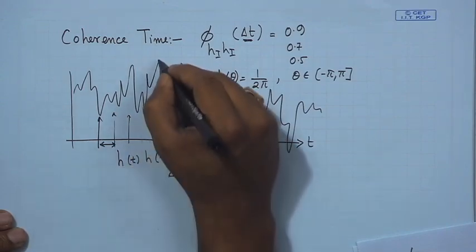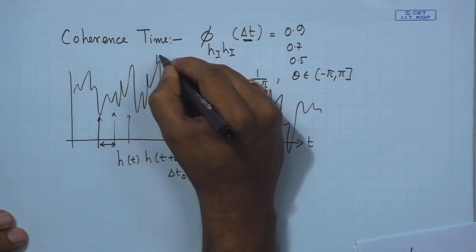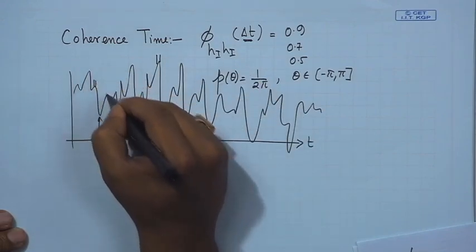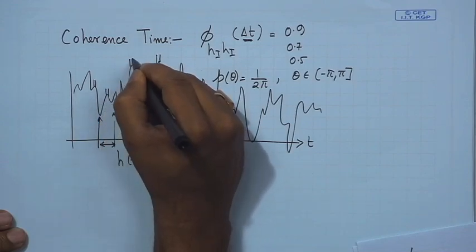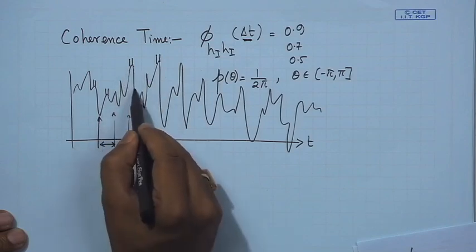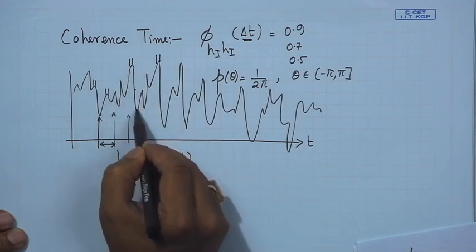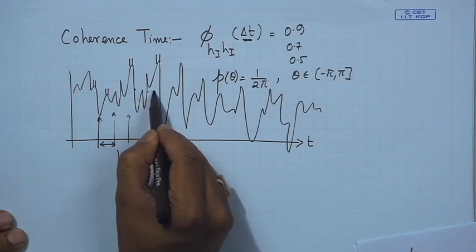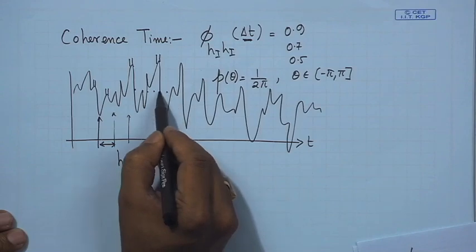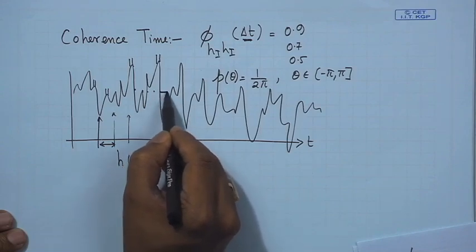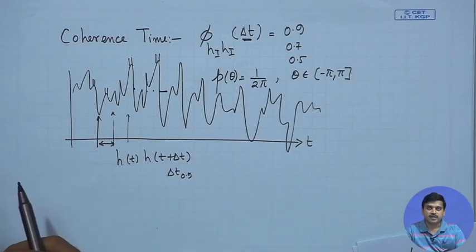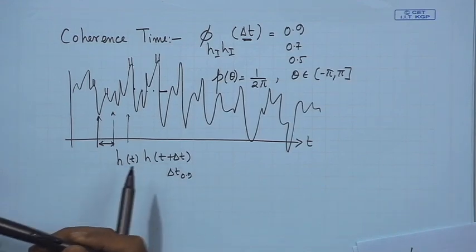So, in this figure we would probably have the separation which is as small as this, which is probably as small as this, where the signals are correlated with itself, right. If I have a point here and a point here, definitely the signals are not correlated, because we do not know at this gap there is uncorrelation. So, this duration of gap at which signals become uncorrelated would be a loose definition of coherence time, or the time separation at which the signal becomes uncorrelated.